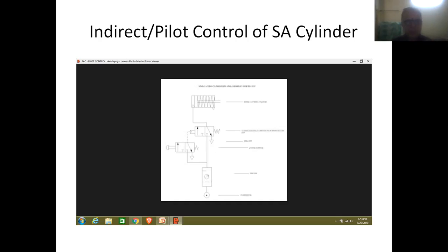And secondly, friends, as usual, a spring-loaded plunger will be placed inside the body of the valve. And here, compressed air or high-pressure fluid coming from the pilot valve will be used for moving the plunger in forward direction. So as a result, the valve will be coming to first position. And in the second phase of operation, supply of fluid is cut off from the pilot valve into the DC valve.